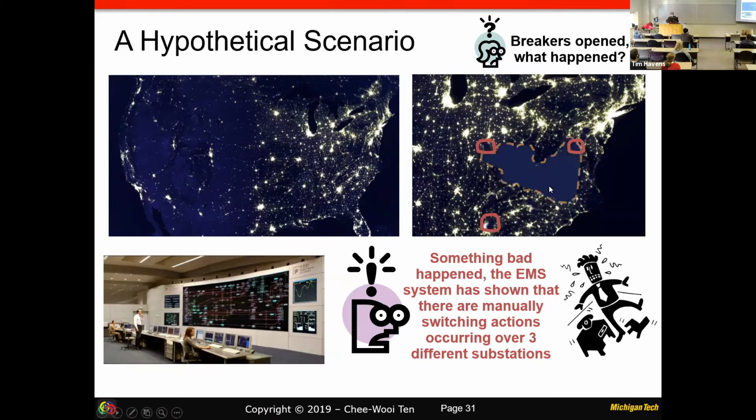That's what we are worried about in terms of balancing the total load and total generation, because when you stress the transfer capability of the grid, a lot of this protective relaying is set locally and is just doing what it was originally told. The threshold values and relay settings are all done locally. There's no coordination. It's purely simple relaying based on local observation. That's how a lot of this cascading happens: you want to protect the expensive equipment locally, but at the same time you want to protect our economy, so you have to make sure all of this is well balanced, and sometimes we come up with special protection schemes to deal with it.